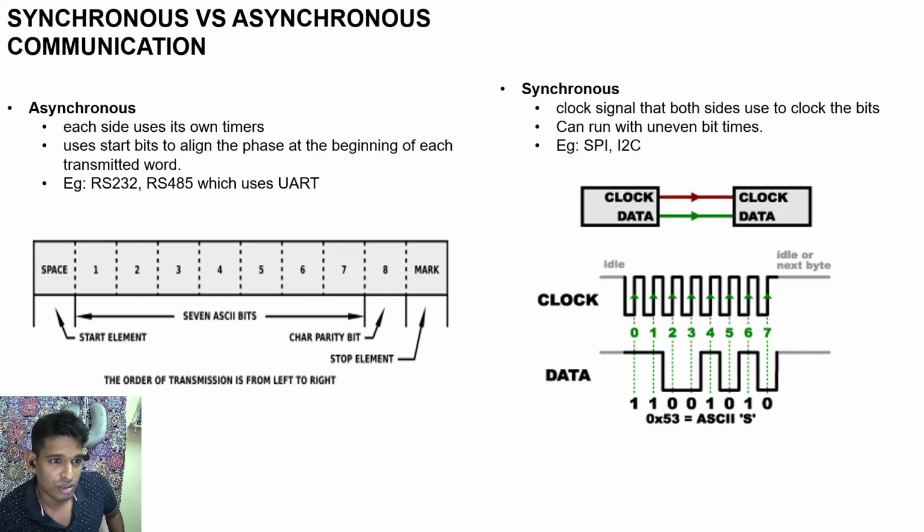So that does not matter in an asynchronous communication. That is what the point is. Your clock has to be absolutely close. It should not be like one is using 100 hertz and the other one is using 200 hertz. That does not make sense. The clocks have to be set to the same frequency, so that even if there is a slight difference in frequency due to some design aspect, the asynchronous communication will adapt to that. But it is not like both sender and receiver are using absolutely different frequencies. They have to have a prior agreed upon frequency.